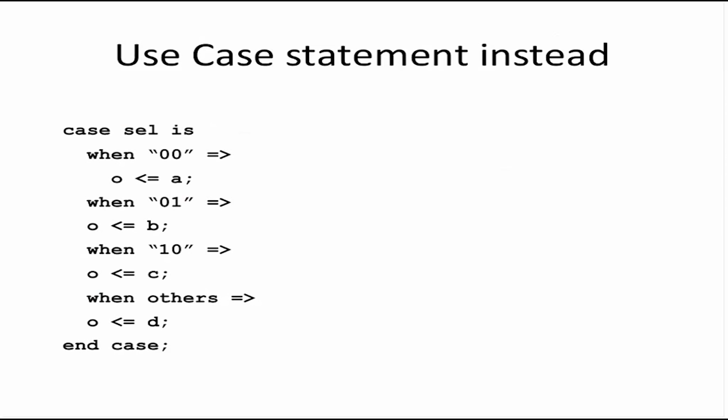So it is recommended to use case statements for such big muxes. You use case statements with 00, 01, 10, 11. There's a keyword called default, which means for all other, remaining cases. Let's say you have a 16:1 mux with 4 select lines, and you're only concerned about what happens to the output in 10 of those 16 cases. You could write all 10 cases here and write default, which will take care of the remaining 6 cases and assign them default values.